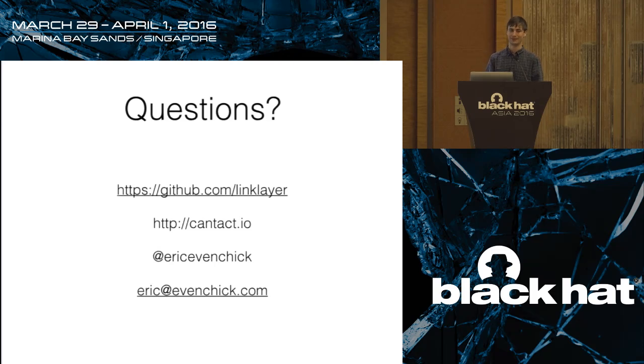But one really big problem is actually what you do if you detect these problems. So if you detect that some attacker is on the CAN bus, what is the next step? Do you shut the car down? Well, that is not really acceptable by any OEM. They never want to shut the car off. I mean, you look at key fobs today, you can do a range extension attack on some vehicles.